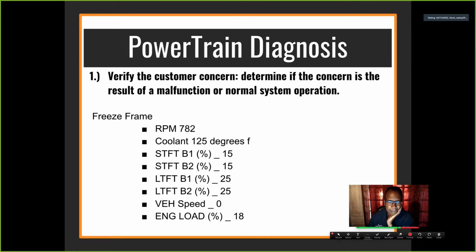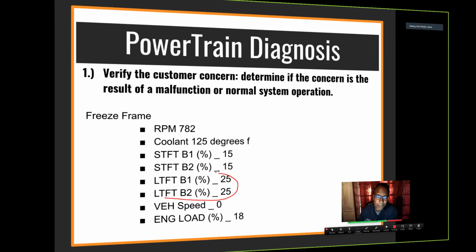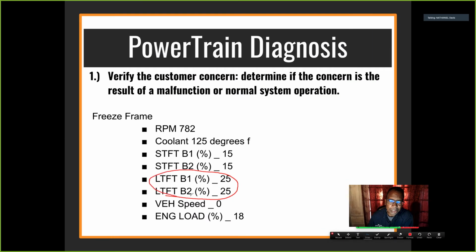And then on the short-term fuel trim and the long-term fuel trim, I would assume it's an open loop, so there would be no control there with the short-term and long-term, right? You're close. No, this works in open loop also. This car is running lean, cold. So in this case, we're adding fuel.